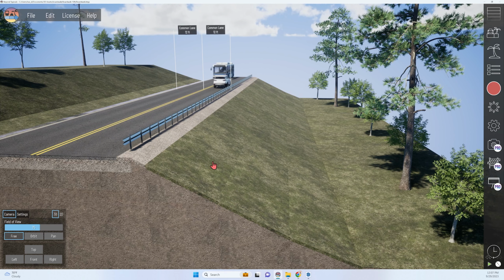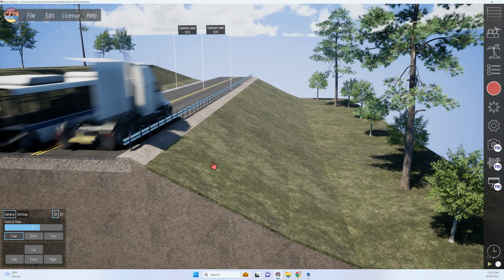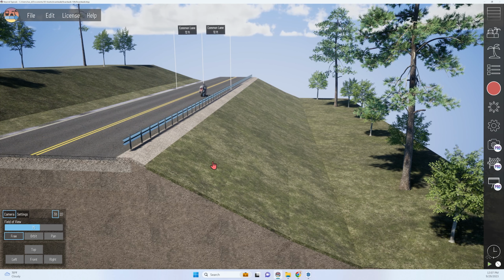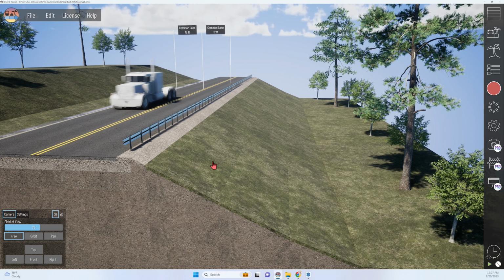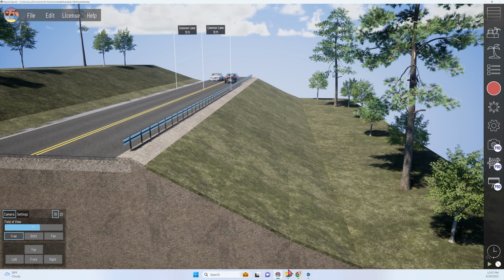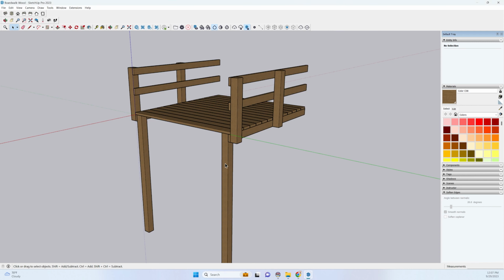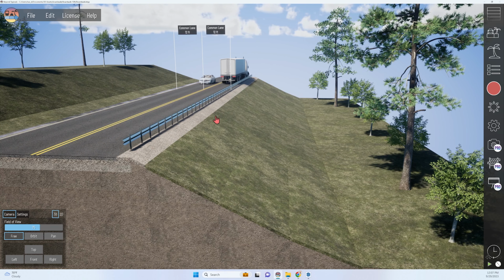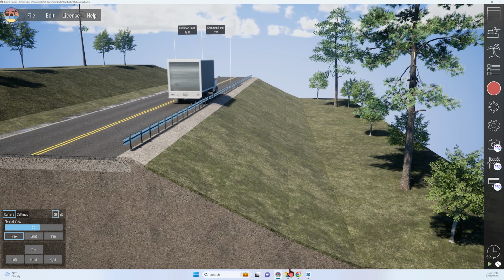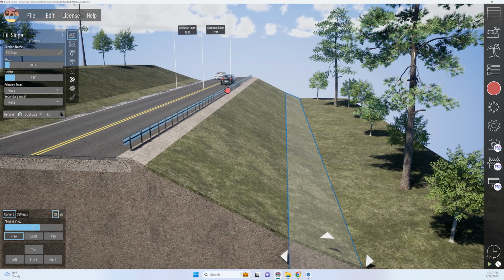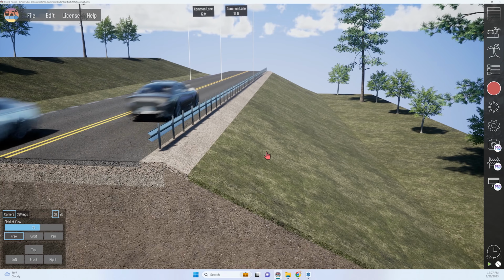I just wanted to point that out where sometimes if you were to export an OBJ and create a Beyond Typicals model with that, if you sent that BTIP file to somebody else and they opened it up, it's going to look for that same location for the MTL and the image. And if those aren't in the exact same place, then it's very possible that that object might come in as a plain white object when they open the file. If that's the case, what you can do is basically hand to that user all of these, and they can re-import this and replace that imported asset themselves to be able to see it.